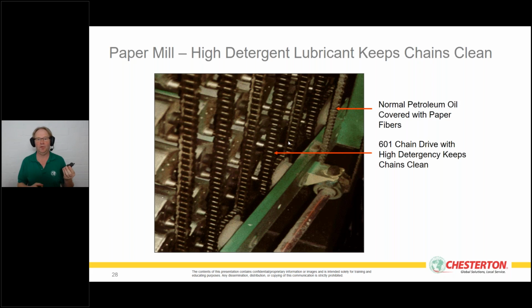The oil they used was too heavy, that means too high viscosity. It couldn't penetrate into the pin and bushes. And when it got rancid, it could not even clean. So what does that mean? We developed a product, or several products, for lubricating chains. And the advantage is, it only takes a few minutes and it actually cleans the chains immediately.